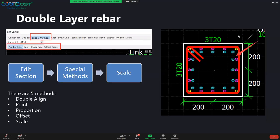So next, double layer rebar. What does this double layer rebar actually stand for? Something like this, basically. So when do you actually face a scenario such as this? When you have a very big column, it requires double layer rebar, where all the rebar labeled in blue color is your second layer of rebar.